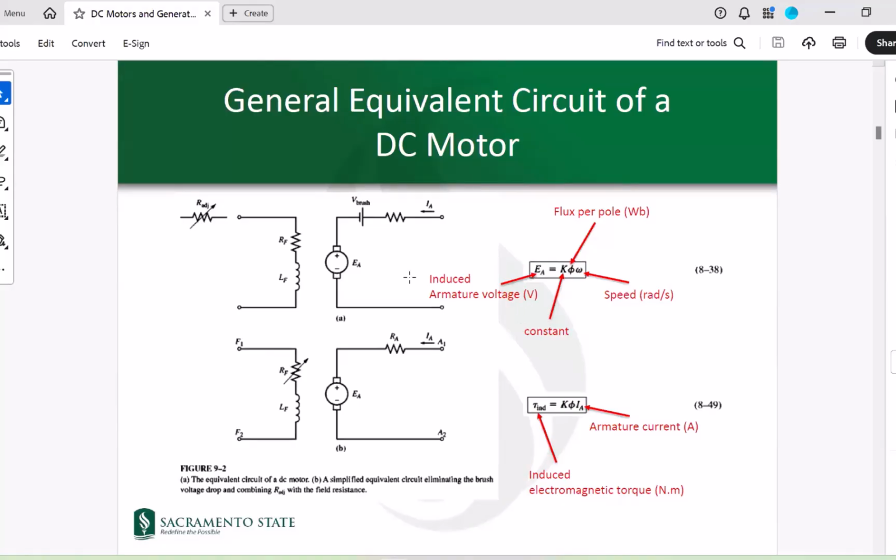All right, now let's look at the armature circuit. In the armature circuit, we have the armature itself, which can be represented basically as the source. And then we have the brush equivalent, which has some voltage drop across it due to commutation that we explained last time. And then we have an equivalent resistance in the armature circuit, which all together can be represented as an RA, equivalent resistance in the armature, and a source. In other words, sometimes we can just ignore the brush if it is small enough.